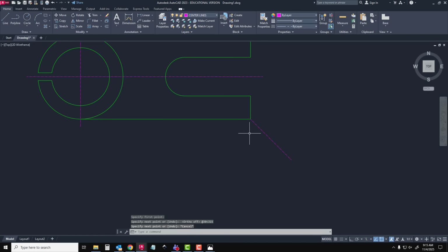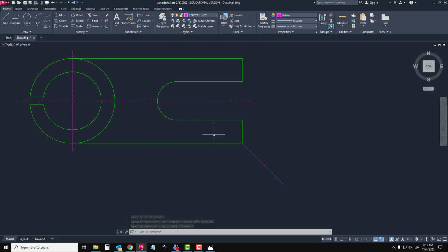Now remember, this is going to be helpful because I'm going to make this an ortho view, but I want to come off the corner, and it makes it a little difficult when I'm coming off a fillet. Now I'm keeping this line right here. Now I'm going to go up to fillets, which you can go fillet or you can type it. I'm going to type it because there's some information down here that it will hit enter. And if you'll notice, anytime you're not sure what's happening, look down here. There's a window here. Even if you click on a line, a circle, anything, it's going to have you look right here. So I want to make a radius. So I'm going to hit the letter R, enter. So it knows I want to make a radius. The radius is a 10, so I type in 10, enter.